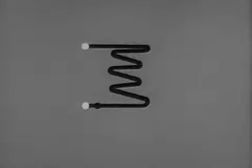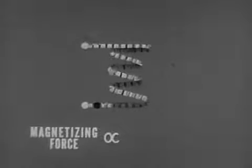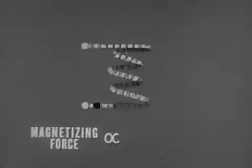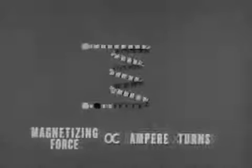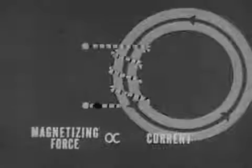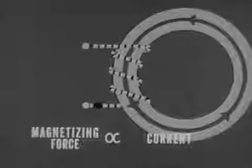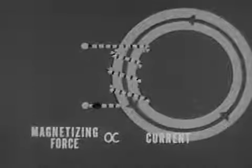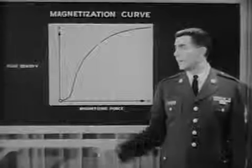Any winding around the core obeys the laws of electromagnetism. The magnetizing force it exerts is proportional to the amount of current flowing through it, measured in amperes, times the number of turns in the coil. Or, as it is usually expressed, the ampere turns. Since the number of turns in this winding is constant, we can simplify the rule here. The magnetizing force exerted by the winding on the core is proportional to the winding's current. Suppose we increase the amount of current. Will the total magnetism of the core also increase? It will, but not proportionately, as we'll see on this graph.